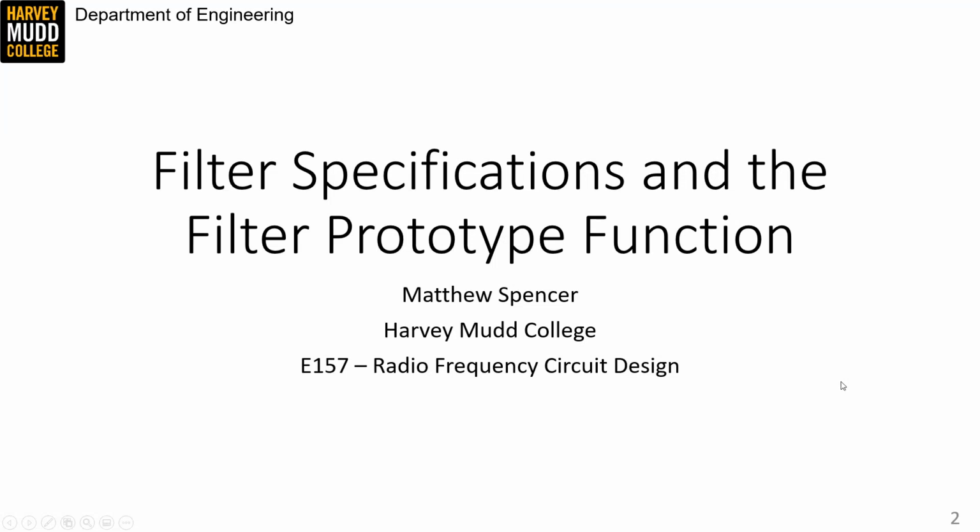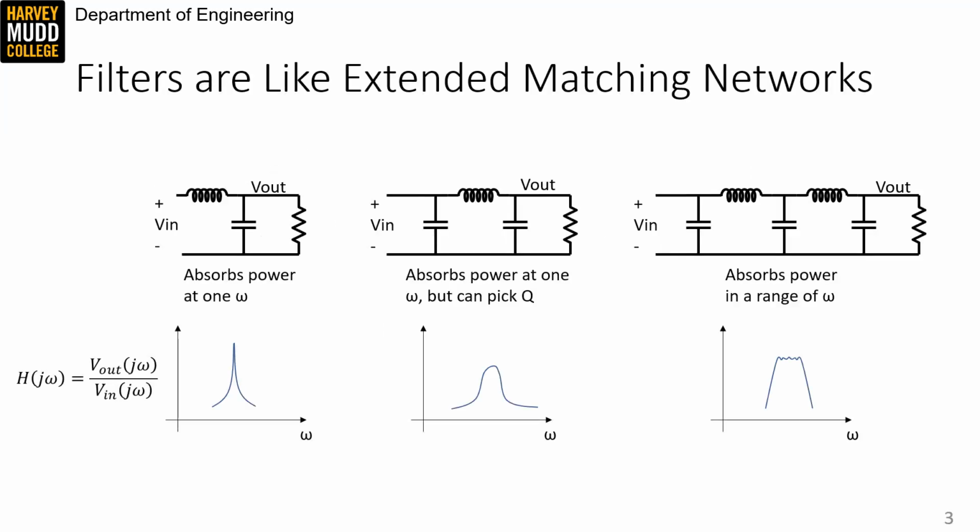Talking about filters by defining a language that we can use to describe them. Filters are a natural follow-on after talking about matching networks because you can think of them as an extension of the same idea. We showed that an L-match lets us absorb energy at one frequency, which is resonance, and reflect it at every other frequency. So we could think of an L-match as a type of filter.